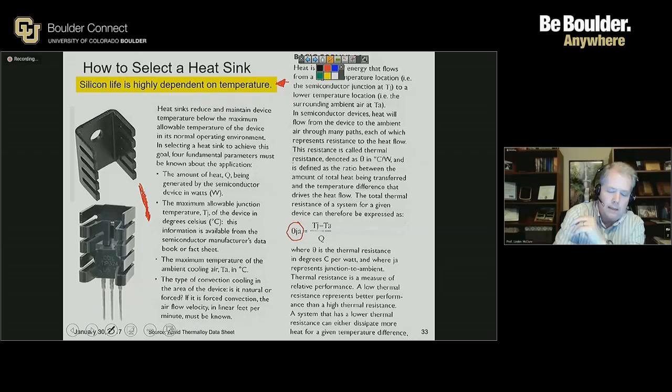So a little bit of spaces in between those two surfaces. And those microvoids are full of dead air. And the thermal resistance of that is very high. So just because you can't see those microvoids does not mean that they're not there and that they're not obstructing the flow of heat. So one of the things that you might do is to use a thermal grease.